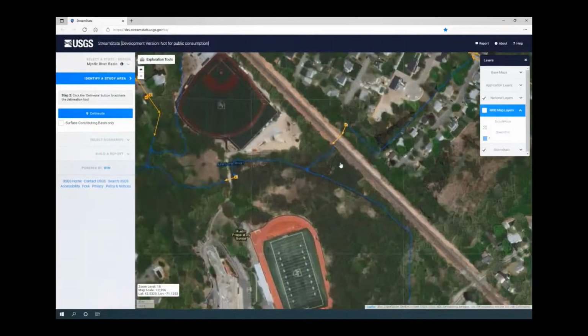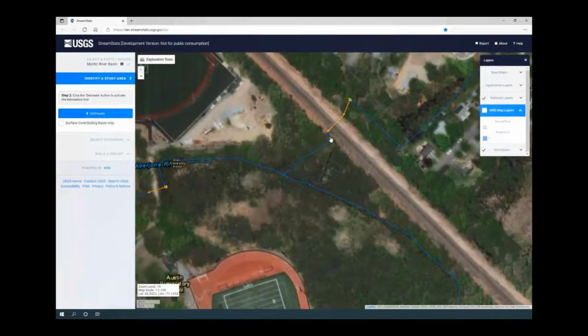And what I'm going to do here is delineate a drainage point downstream of this railroad crossing on a stream flow. You can see we have a culvert mapped underneath. The culverts are also part of the storm drain data set. They're uniquely attributed, but this culvert makes its way under the railroad.